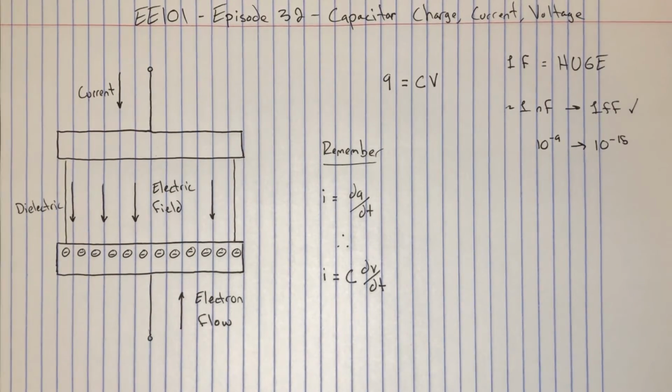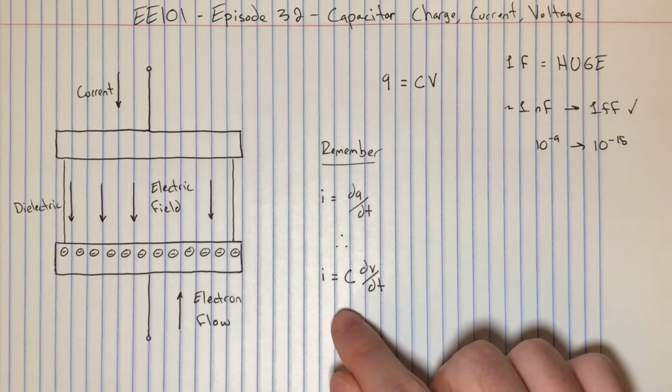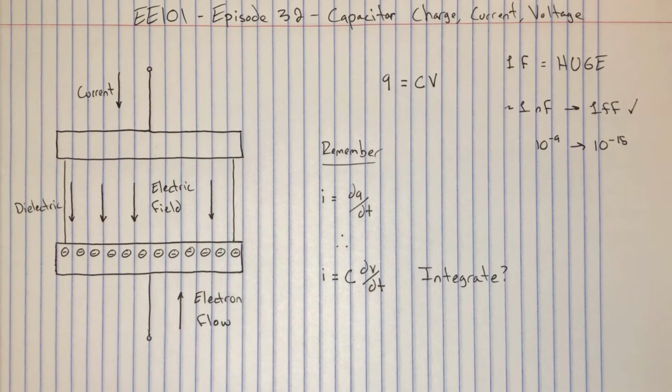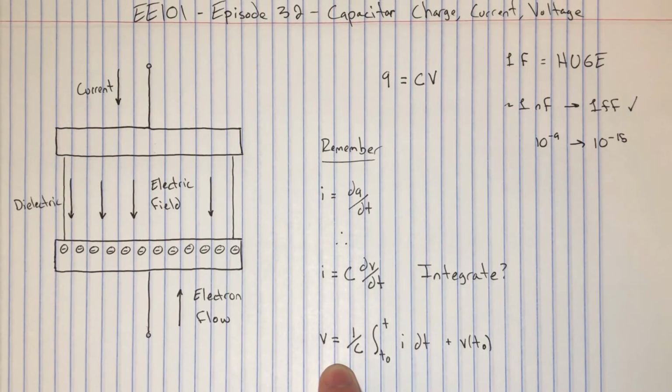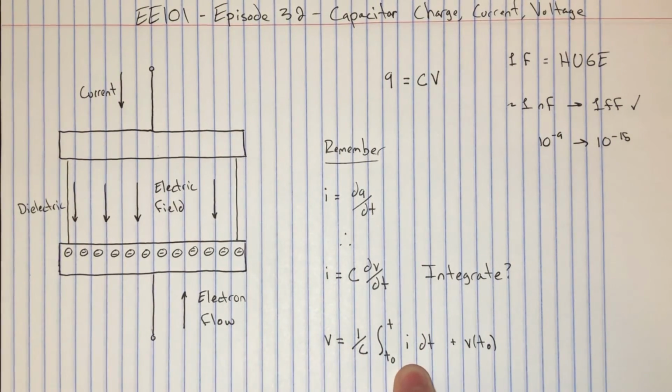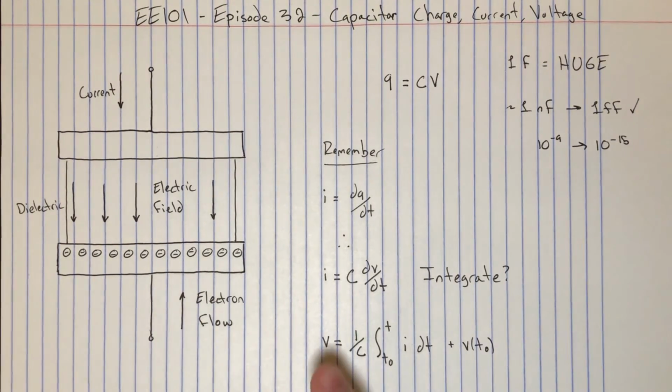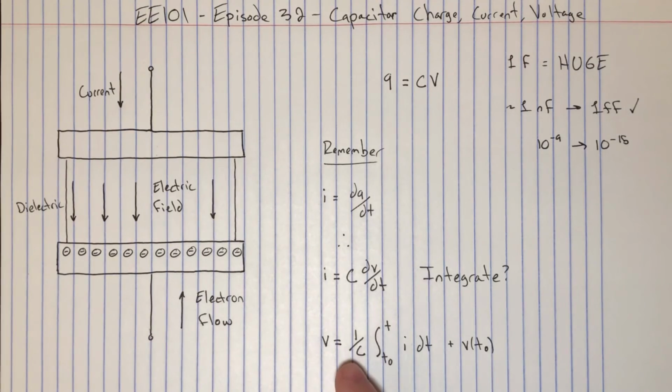Okay, and the last thing I'm going to include in this video is an inversion of this formula to instead express capacitor voltage as a function of its current. And yes, it is as simple as integrating what we already have, but you have to remember to include a constant voltage to represent the initial condition on the circuit. The resulting voltage will be a function of both a change in current over time and an initial voltage. Now for simplicity, we usually wind up saying that this initial time t0 is just 0, but I've kept it in here for generality. And also you'll often see voltages and currents for capacitors written as V(t) and I(t) to indicate they're functions of time, but I've just happened to leave that out here.